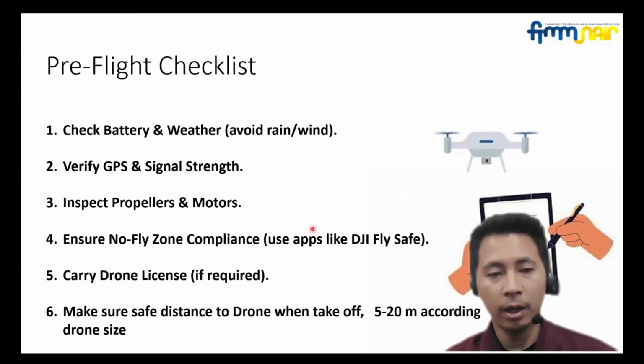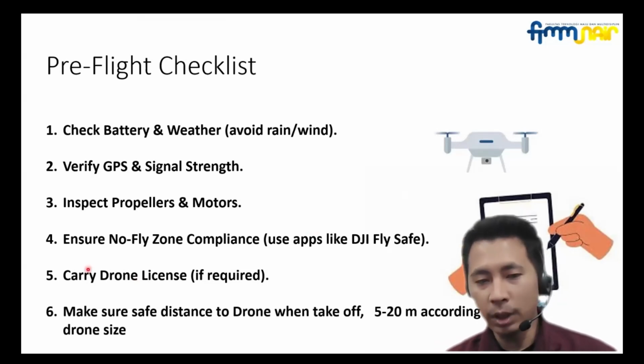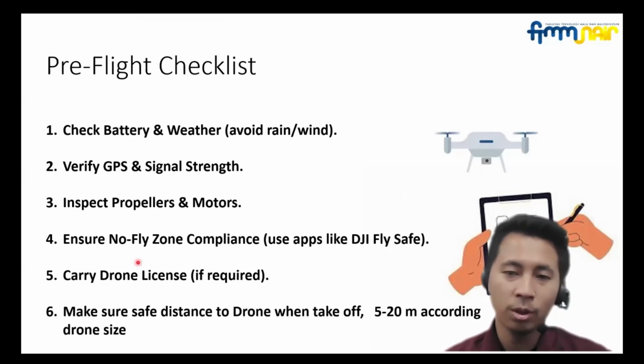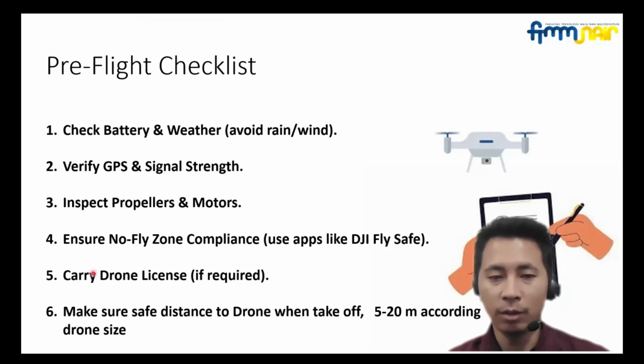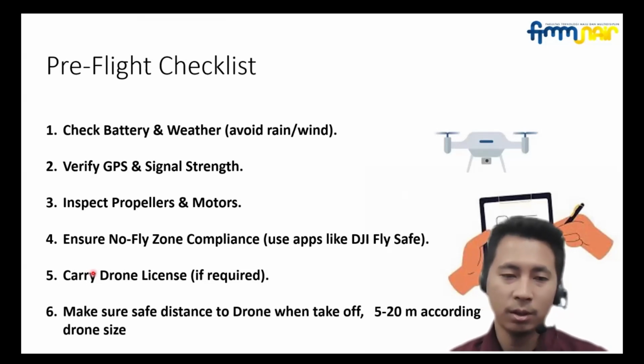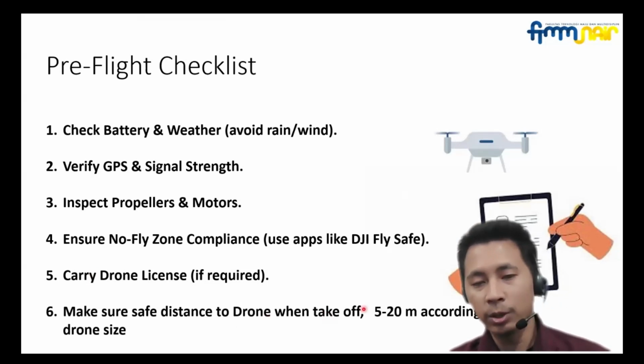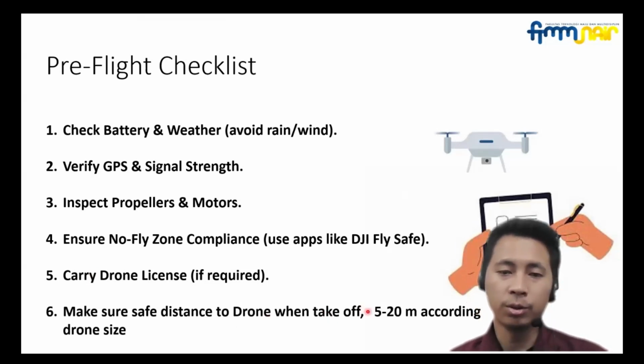Okay, and if needed you have to carry your drone license. In Indonesia there is a drone pilot license. If required, you have to show that if something happens. Make sure to keep a safe distance from the drone when taking off, around 5 to 20 meters according to drone size.